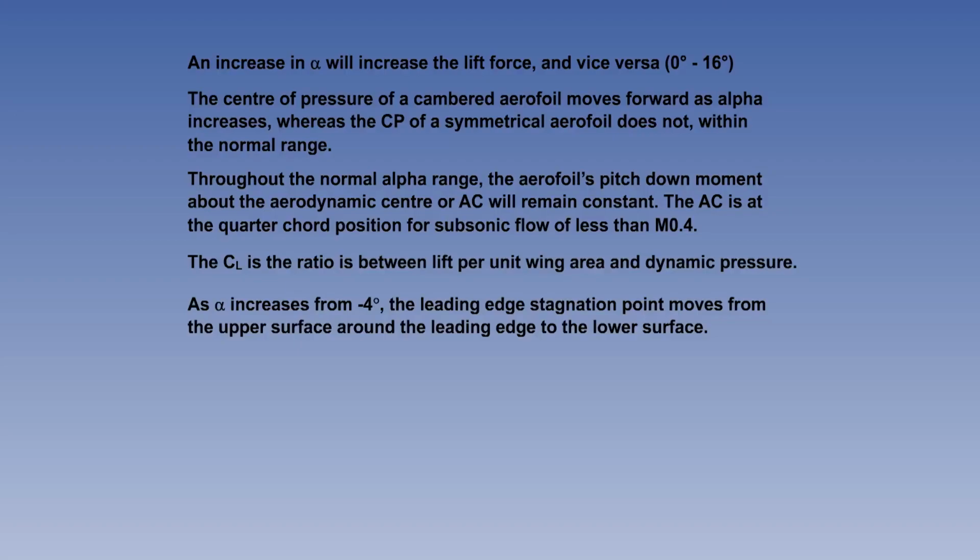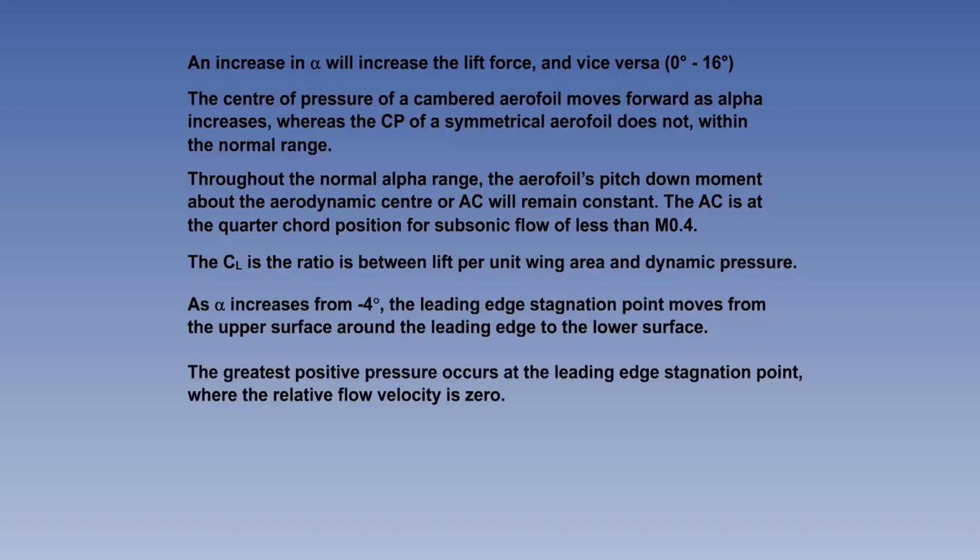As alpha increases from -4 degrees, the leading edge stagnation point moves from the upper surface around the leading edge to the lower surface. The greatest positive pressure occurs at the leading edge stagnation point, where the relative flow velocity is 0.